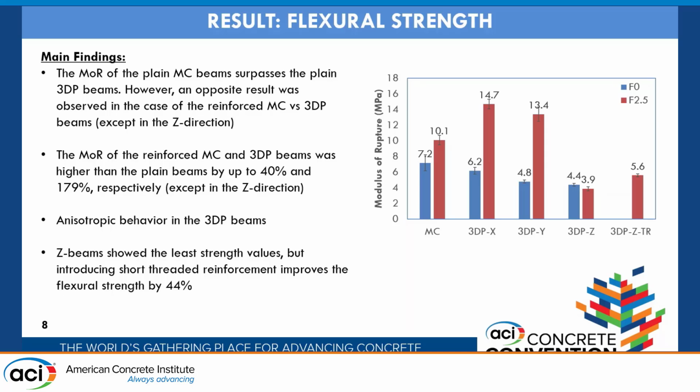And then in converse, in the fiber reinforced specimens, the 3D printed specimen actually outperformed the mold cast specimen, even with the presence of these interfaces. And this was attributed to the preferential alignment of the fibers at high dosages in the 3D printed specimen.